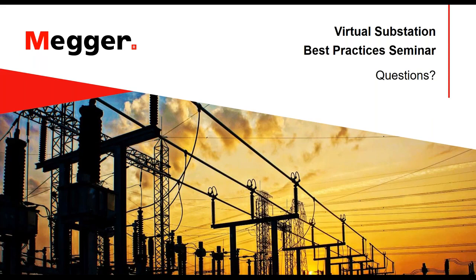So I highly recommend against using 10 kV equivalent values when comparing excitation current values. You want to compare test values performed at the same voltages.